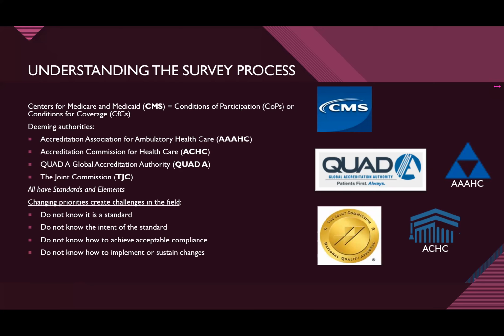Okay, so looking at generators, people look at generators weekly and monthly and quarterly and annually, and then every 3 years. And the biggest challenge I see with outside generators is debris. Debris blown in from neighboring land. I saw a generator that was near a gas station. And so the paper wrappers and things were all around the generator, and the generator needs to be clear of combustibles because the generator gets hot.